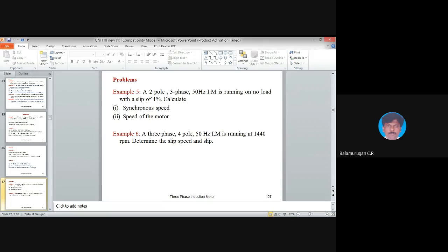Suppose if one parameter is 0 we will add the other two parameters. And here all these three parameters are available. So already you know phi y is equal to phi m. And you are going to take the resultant only between phi x and phi z. So what are the parameters available? That will be 2 into phi m by 2 into cos of 120 divided by 2. What is the angle between phi z and phi x? It is 120 degree. So you have to take 120.